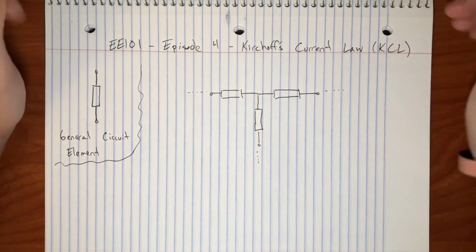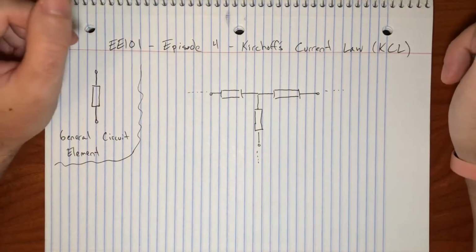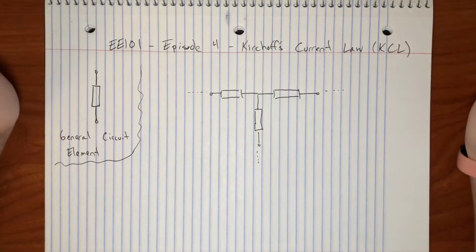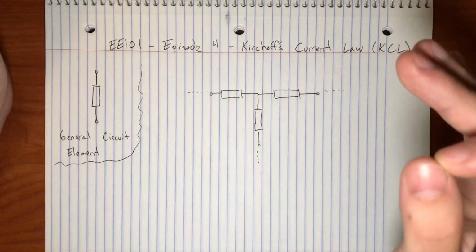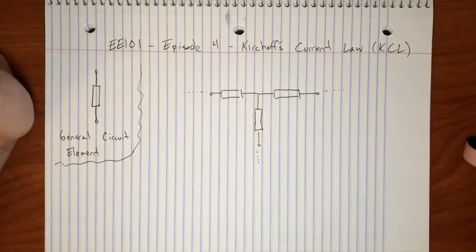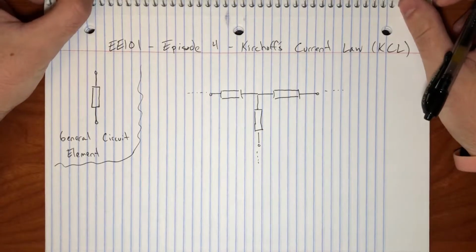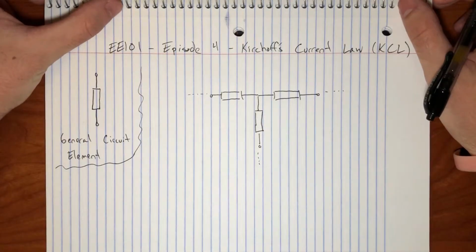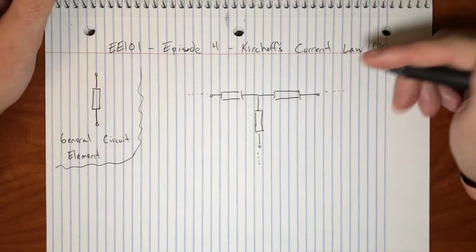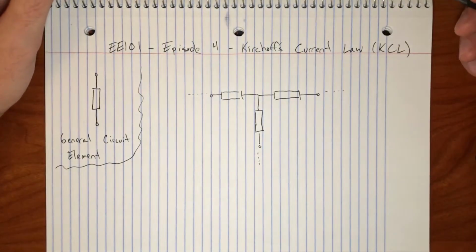And I know that sounds a little weird, and I said some things in the video about voltage that appear to contradict that, about how anytime you have current flowing through a circuit element, there's a voltage across it. And that's true except for the case of the ideal conductor. But lucky for us, I don't think there's really a contradiction there, because ideal conductors don't exist. We fabricate them in our analysis or our schematic modeling just to help us out and simplify things.